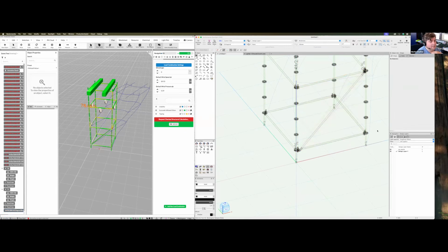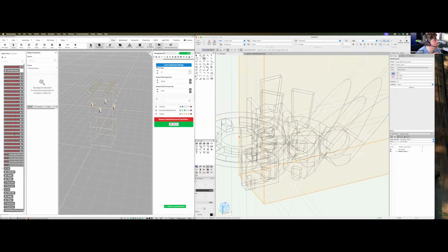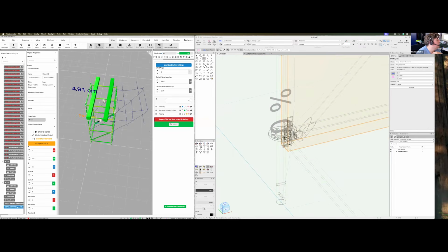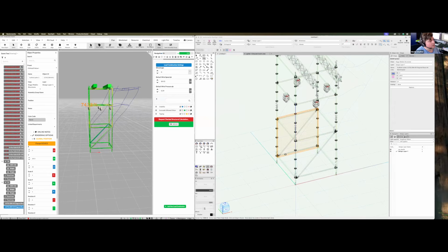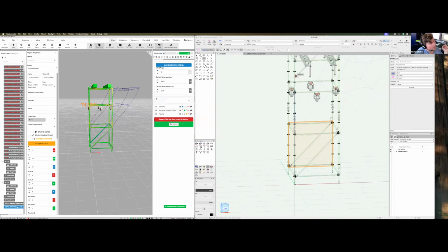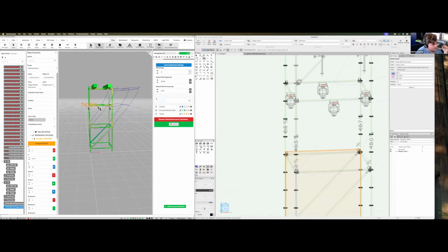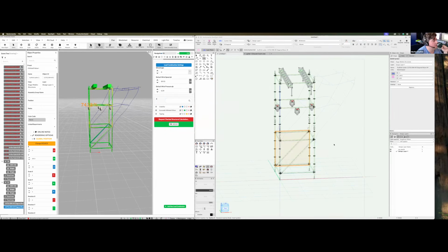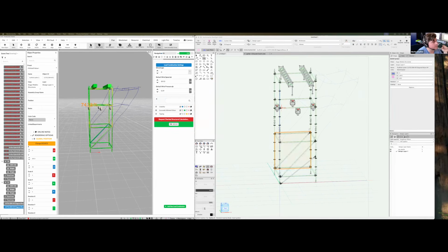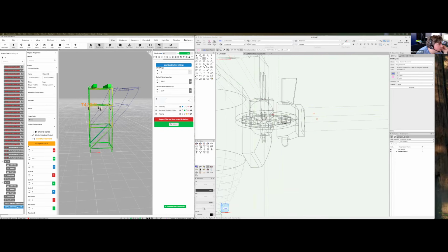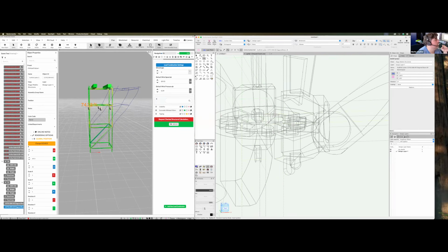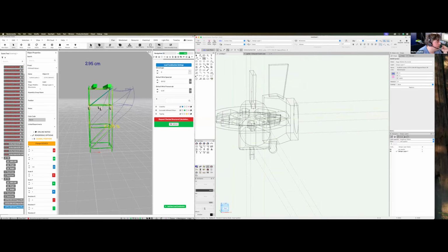Next, same thing, I'm importing this and placing it in here so that we have it like this. What I want to do is add something in here, and that's only 1.5. Important thing: every distance between this is 0.5 meter. So we now need the 0.07 by 0.5 meter, which I've imported from the resource manager. I'm searching for the point in here, the red point, double clicking it, and I have it in here 1, and in here 2.